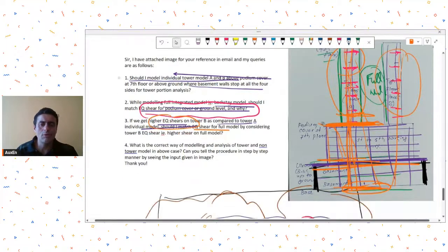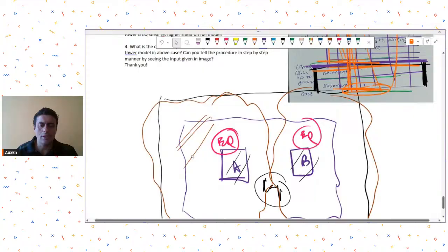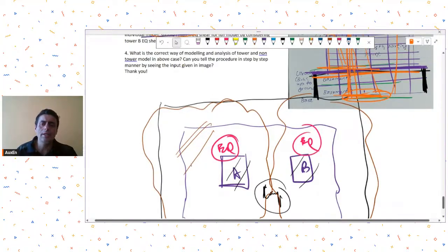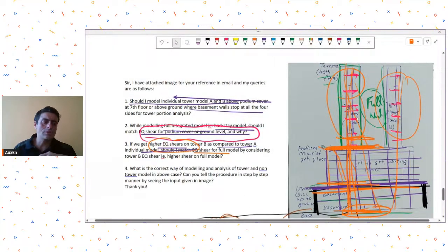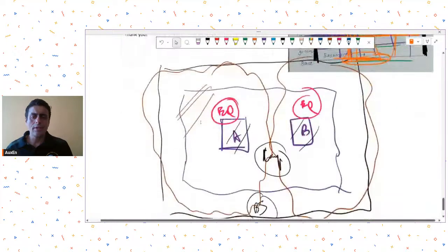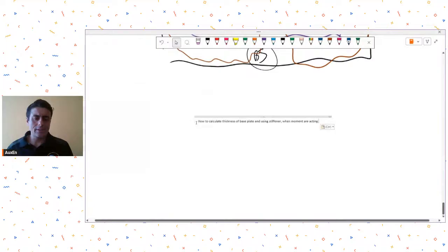From there you will get proper story forces on each floor separately. So wind is comparatively simpler over here, because those inputs you will be getting directly from a wind tunnel test. This earthquake becomes slightly tricky, especially in the backstay analysis.